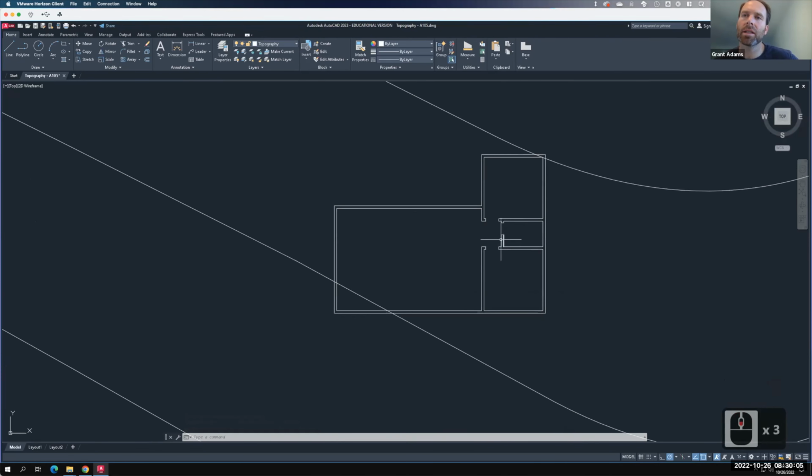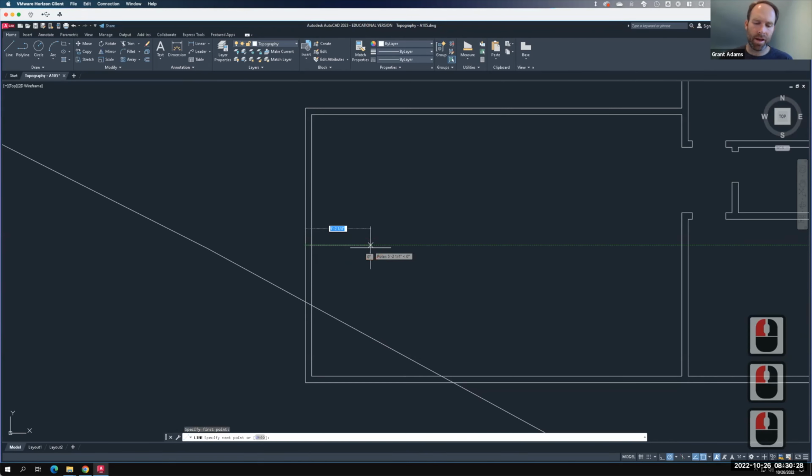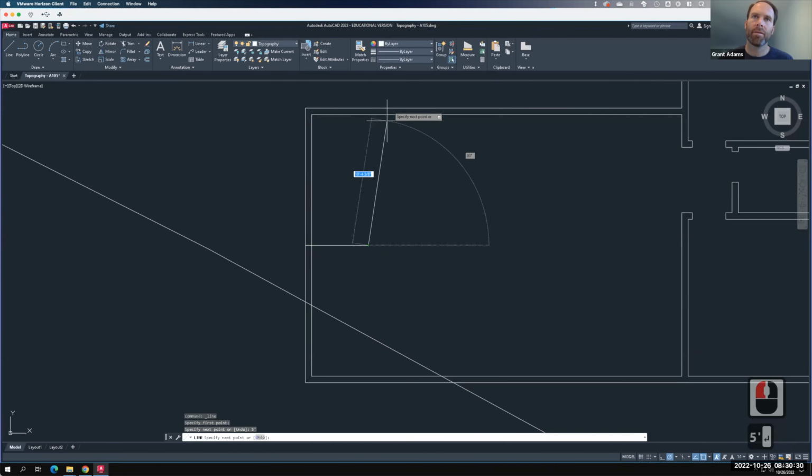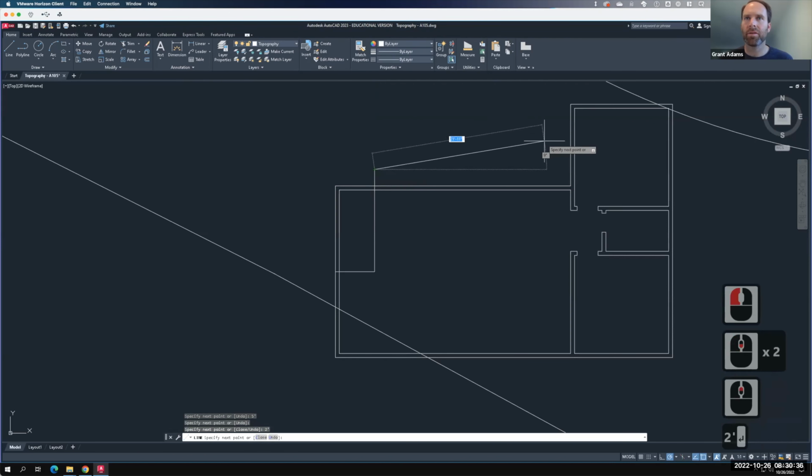So in this context, I'm starting to create that shape. Now, maybe I need an entry, or I want to create some kind of an entry porch or something like that. Well, maybe I need to modify this shape. Maybe I need to add. Let me turn on my midpoint snap here. Maybe I need to have this wall come in by 5 feet. And I need to come up to there. And maybe that means that this actually gets longer. So we come over by 2 feet there.